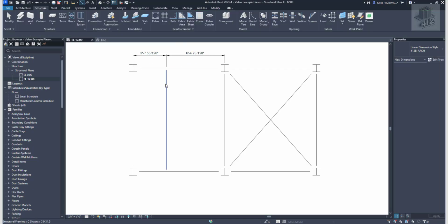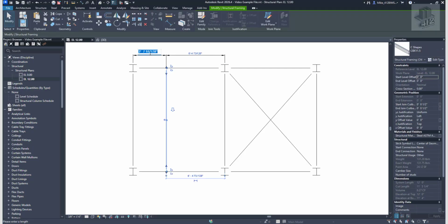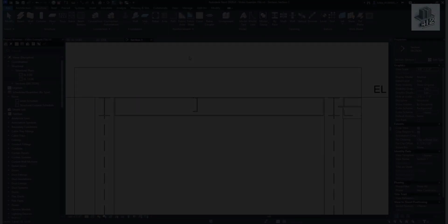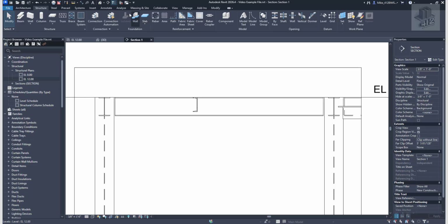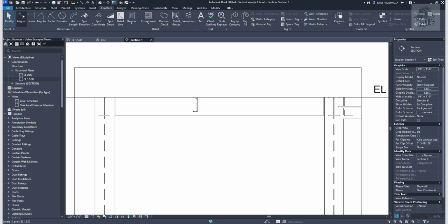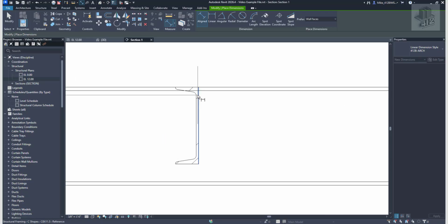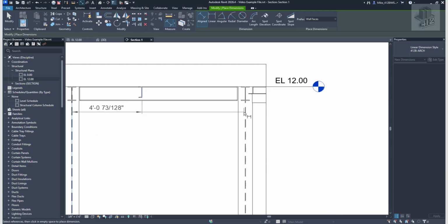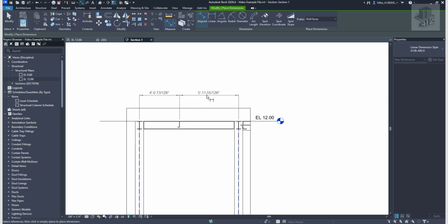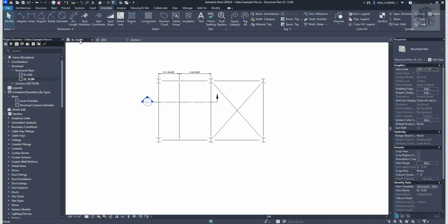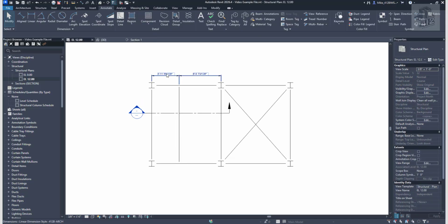So now, if you want this to be 4 feet, right, you think you're good. But when I cut a section, and I go to put the same dimension going from center of column to back of channel to center of column, I don't get those numbers. So then you run into the tug of war. You run into where you make this 4 feet. Then you go to your plan view and you've got bad numbers again.